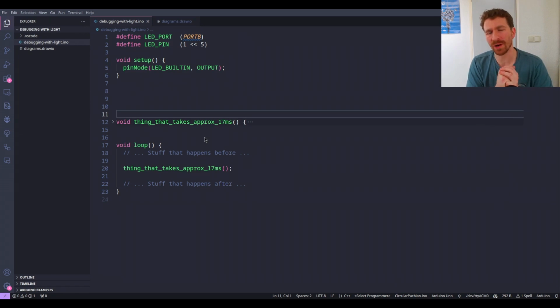If you were to hold a camera up to that, if I was to even show on the screen what that would look like with a camera, I'm not going to be able to show you it, because even a camera that runs at 60 frames per second is going to be extremely close to the frequency of the actual change that we're trying to observe. And because of that, we're going to alias, and we're not going to see that change in the frequency, because we can't observe a 17 millisecond signal on a 16 millisecond update rate, right? That's just not going to happen.